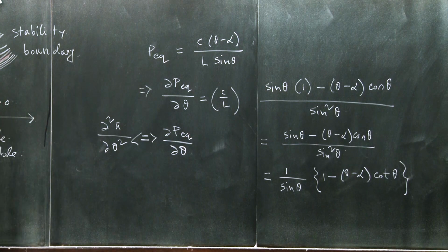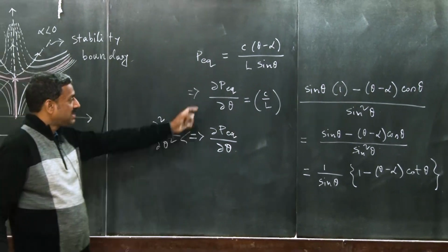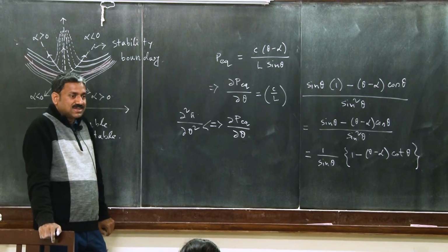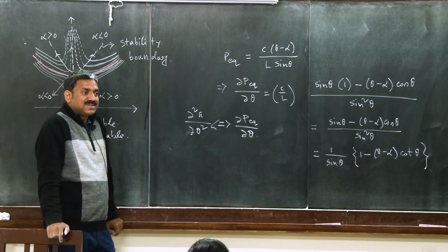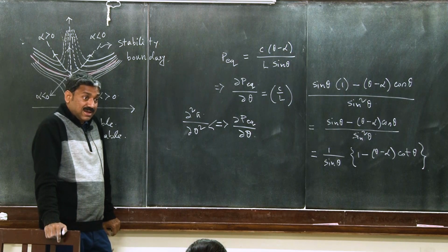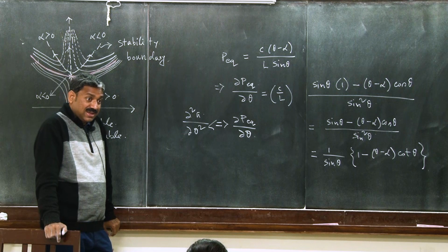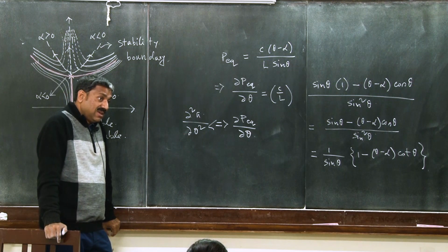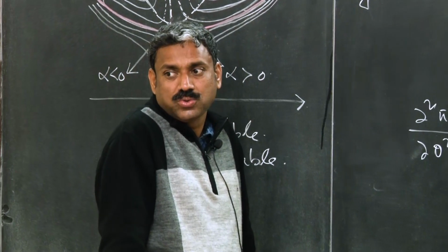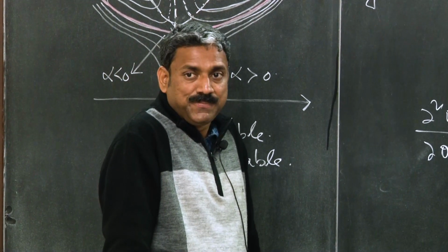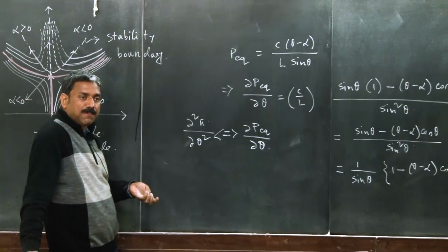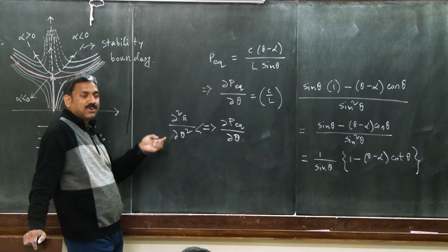Then see, when you differentiate once again, for ascertaining the stability boundary or stable and unstable transition, you have to explore the second derivative of the potential energy function, right. And when you are obtaining del 2 pi by del theta 2, then on that you have to impose the equilibrium path as well, because the first system has to satisfy equilibrium, right. For this system it is simple, because del 2 pi by del theta 2 you can easily find out.